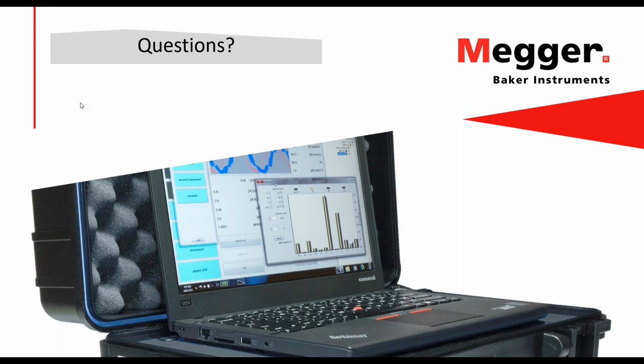On the underside, we're less generous. We do the 95% under voltage or 90% under voltage would give you warning levels. So we do shorten that a bit. And all of these are adjustable to whatever limits you want to put in.